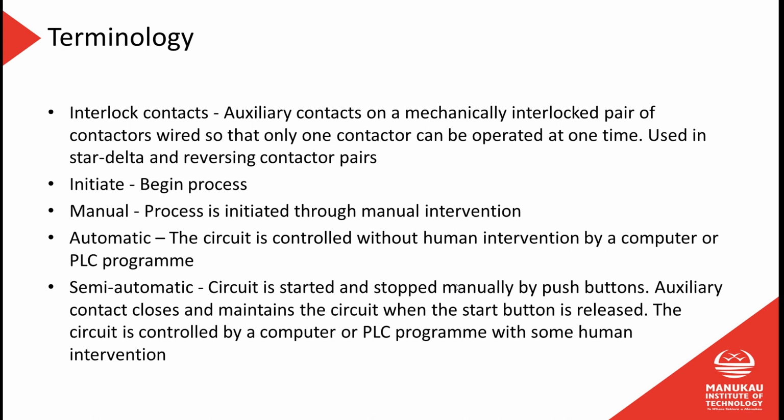Now, without being able to show you or draw that picture, I can tell you that when you set up a forward and reverse circuit like that, if you somehow manage to switch both of those contactors on at the same time, you would end up shorting phase to neutral. So you have an interlock in there. We will definitely cover this when we get back to class, because there's just no way that I can do it from this angle, I'm afraid.